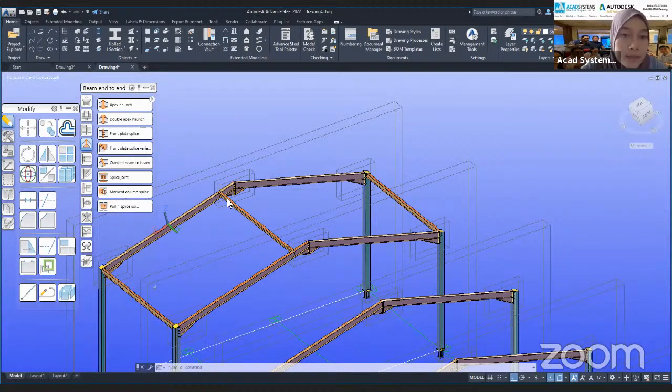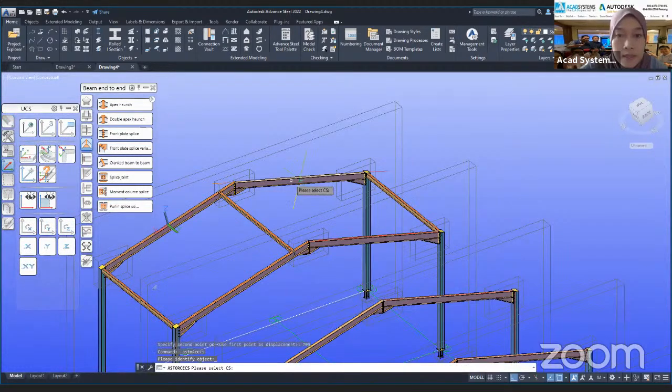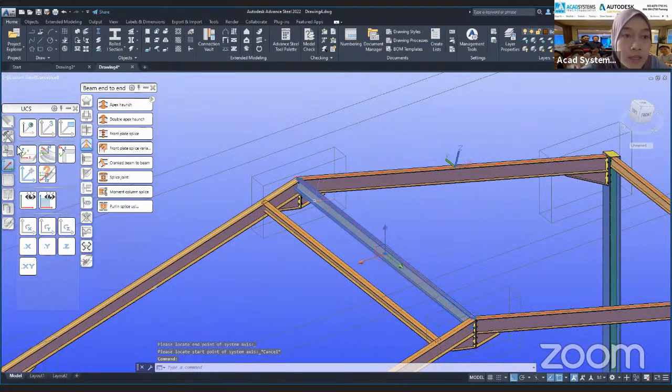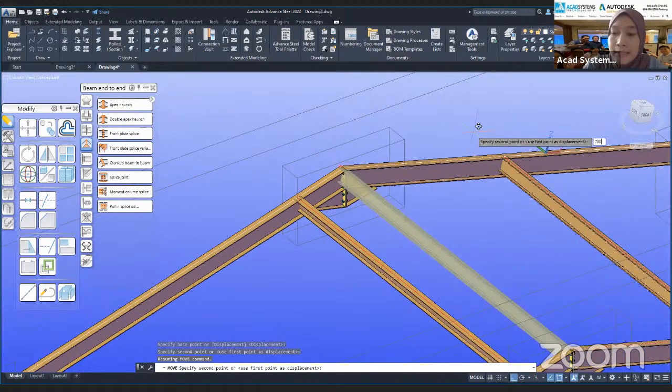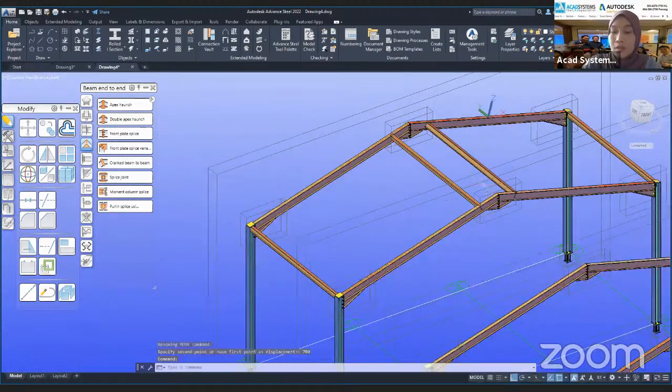Okay, so again, let's create some more UCS here. Change the UCS into this beam and choose this line and right click. All right, so add some more of the roll section here, starting on the node between this and then this node. From there, click on here, modify, move, and 700 also. Enter. All right, so this is what it will look like.